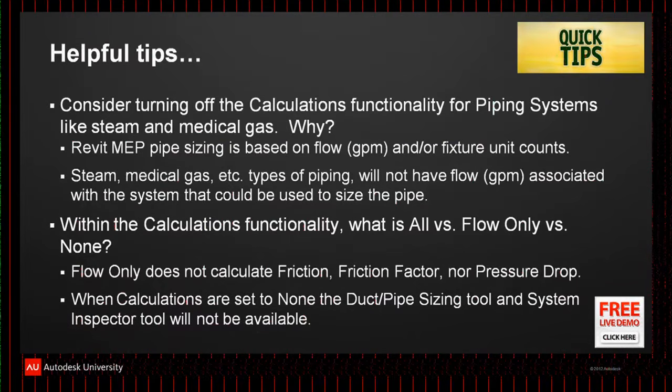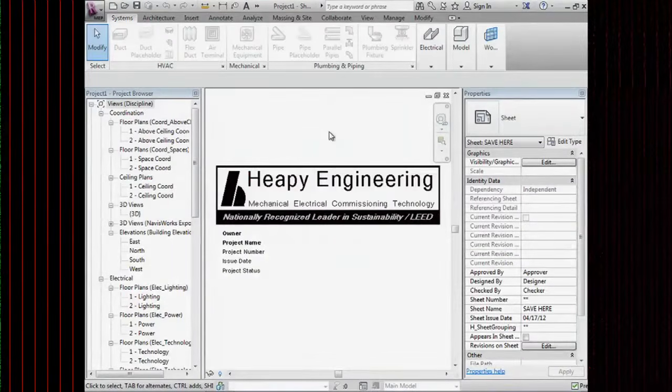Thinking the same calculation through the whole building makes sense to a point, until we start running different noise criteria. So the calculation is only going to be based on, and we'll get into that, but noise criteria is not one of those. So you won't get regenerated noise anywhere inside of Revit. It's not going to tell you what the radiated noise out of the duct system is.